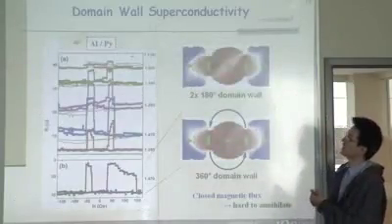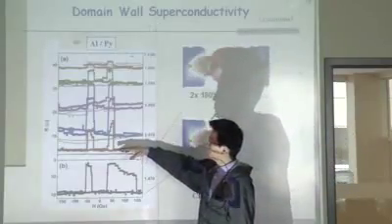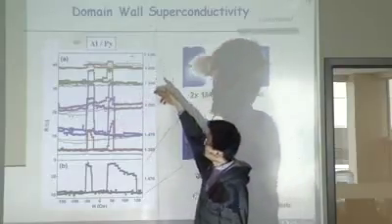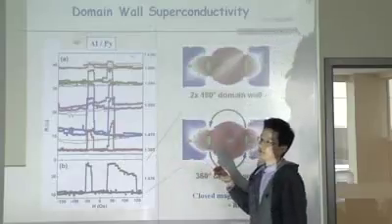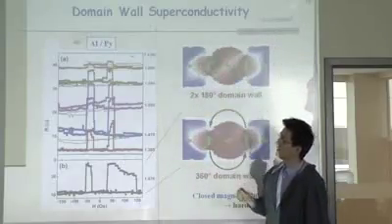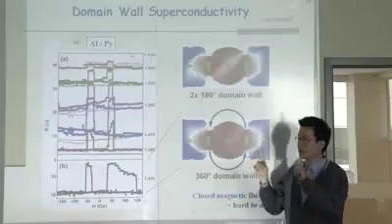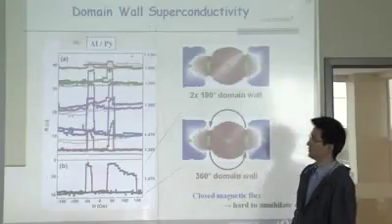This slide shows you the actual result. As you can clearly identify, there are two very well-defined low and high resistance states. This is as a function of temperature. This is magnetoresistance versus field for different temperatures. These two resistance states correspond to when the domain wall is in the middle of the wire or when they are driven out of the system.